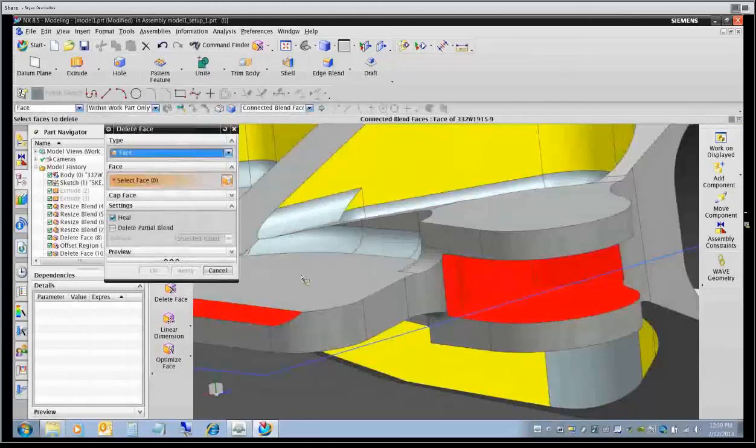So if I go back and just delete this guy here, oops, second here. We're going to go back onto here, and instead of all the connected ones, just a single face. That's really what this error is complaining about here. So let me just repick him again here. We'll say delete a face. Make sure we're here on a single face when we go to pick him.